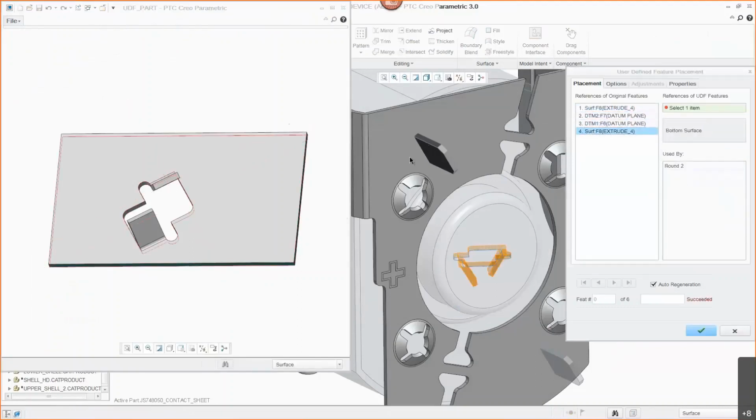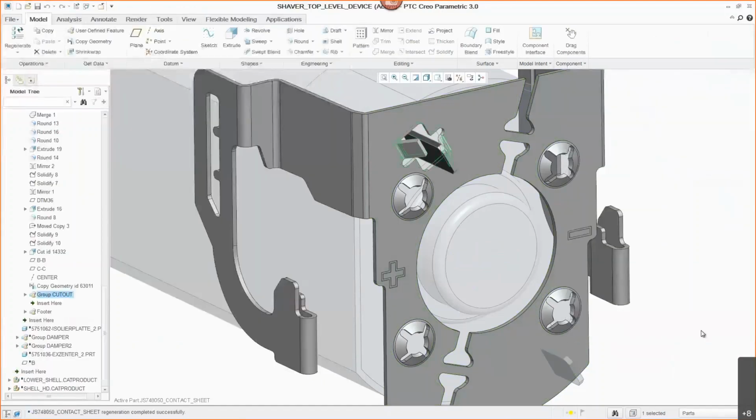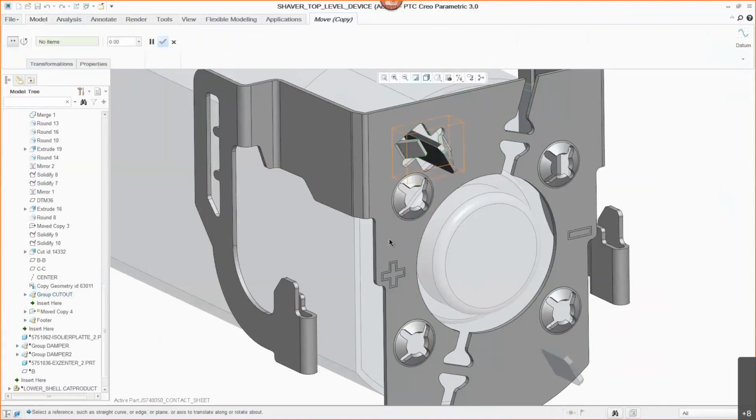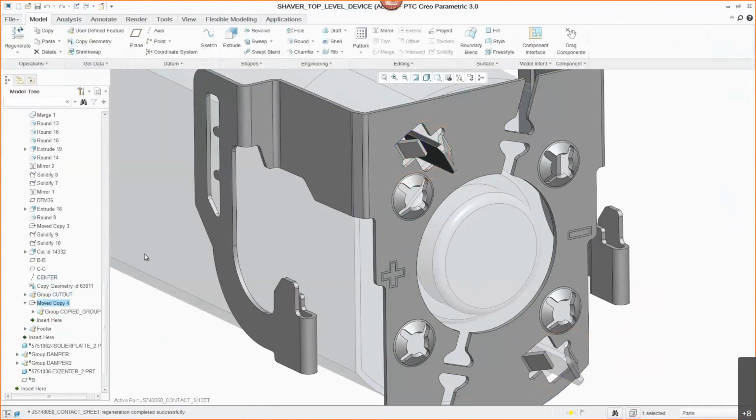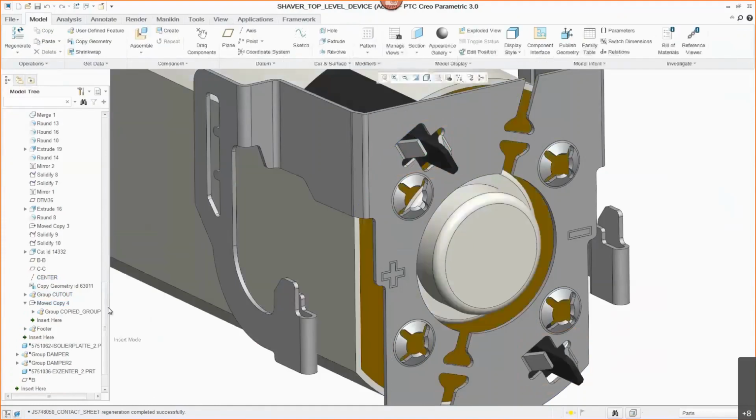This is a user-defined feature, so if this is a cut you make all the time, have those definitions already predetermined and then just choose the reference geometry. In this case, the reference geometry is the surfaces from the imported part. And then if you want the second cut for the other tab, 180 degrees would do the trick.